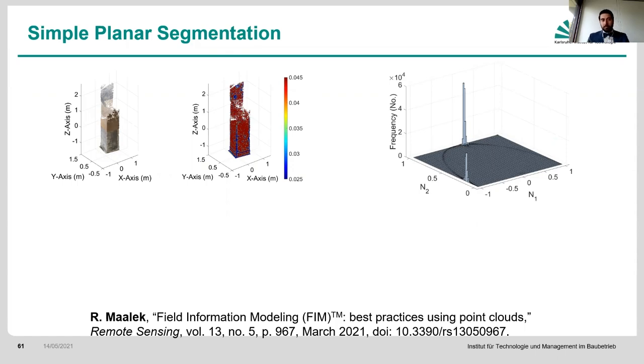So the normal vector, once you get it, how these types of objects are detected and how I have proposed to detect these types of objects. These are planar surfaces, let's say. These are floors. These are walls around it. The simplest and the most accurate way is this: to be able to find where the majority of the normal vectors are directing to.